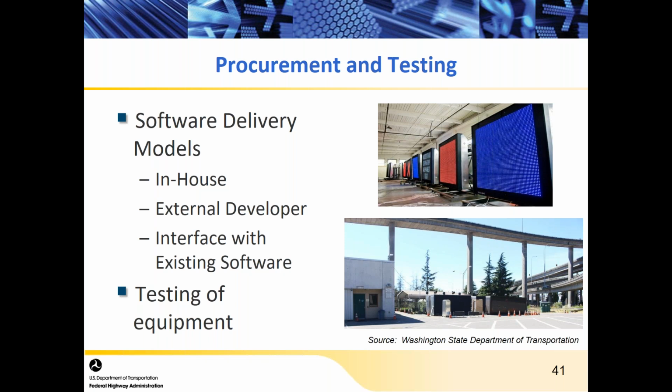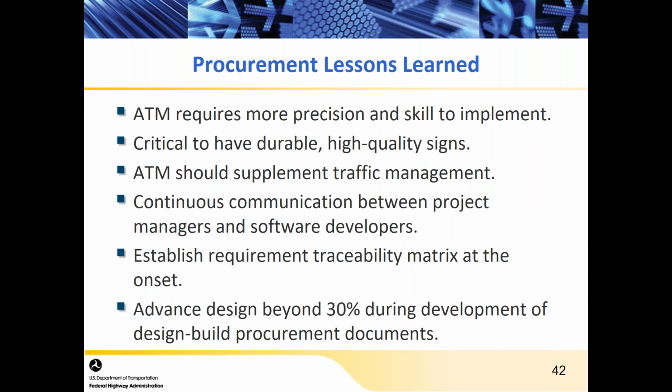Maintenance becomes an issue as well with some of these signs, because it's a new thing, and your technicians may need to be trained on how to maintain these signs. If they're over the lane, that does impact maintenance activities and whether or not you need a lane closure. So there's trade-offs associated with doing a sign bridge that goes all the way across the facility as opposed to just a shoulder-mounted sign. And how easy this technology is to replace, and what to do with legacy systems.